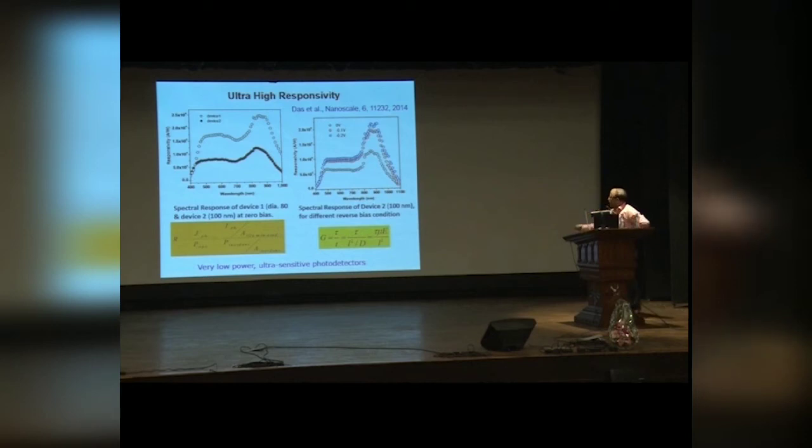So of course the mu and tau are constant. What is varying is L. First, as I said, there are no recombinations because the nanowire diameter is much less than the minority diffusion length. Of course, there will be recombinations if there are some traps. And the electric field is very, very high. The nanowire diameter is very low.